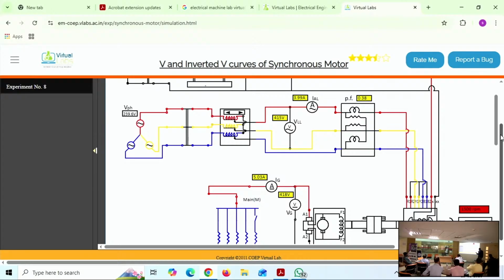So now the rotor starts rotating. Now we need to give the excitation, DC excitation, to the rotor once it is reaching near the synchronous speed. If you have already done this experiment at your institution, you can feel the alignment of the rotor with the stator field. Right? Initially the motor starts, but during synchronization with the RMF, the rotor gets aligned, then locked. Now it will again rotate under steady state.